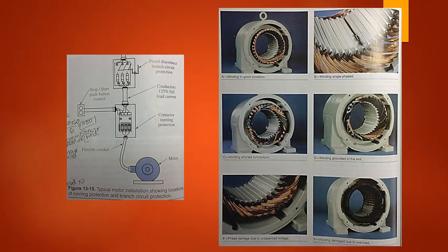The full load current of a motor is the current the motor is expected to draw while it is under full mechanical load. A table saw, for example, can be rated at 12 amps for full load condition. This means that when the saw is cutting the maximum size of wood it is designed for, it will draw 12 amps of current at the recommended applied voltage. When the saw is turning but not cutting wood, the amperage will be small in comparison, maybe as little as 1.5 amps.